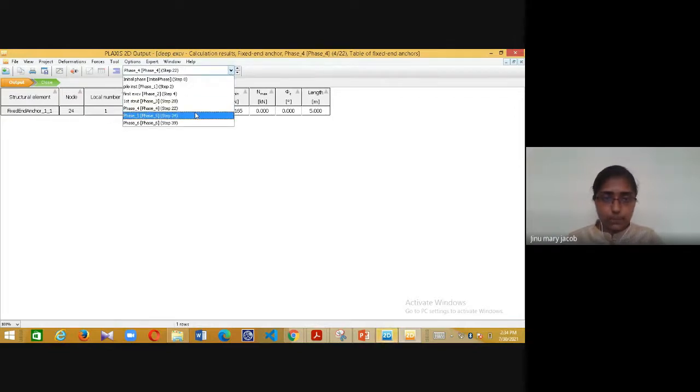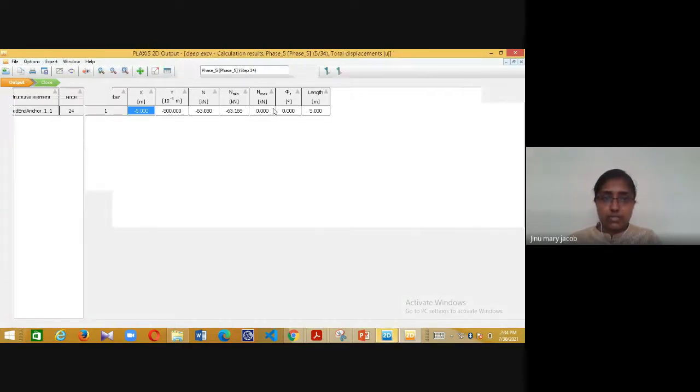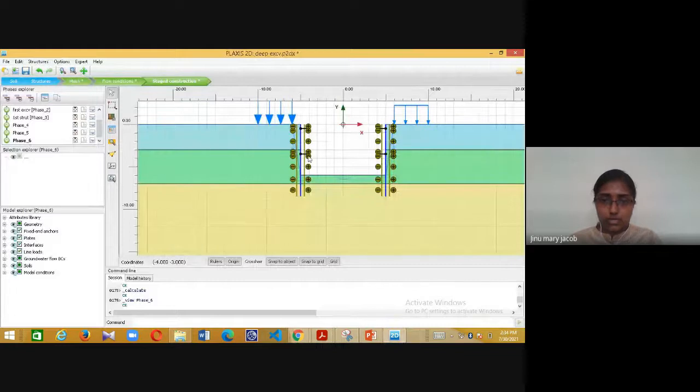So usually the procedure we follow is, from Plaxis we extract these results, what is coming onto the struts and plate, and it will be given to a structural engineer for design of the struts. So the structural elements get designed by a structural engineer. The influence due to the soil gets determined by a geotech engineer. That is the procedure we used to follow, but it depends upon the industry where you're working.